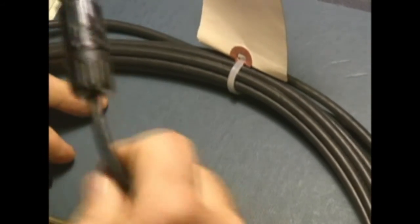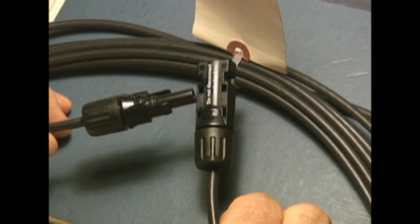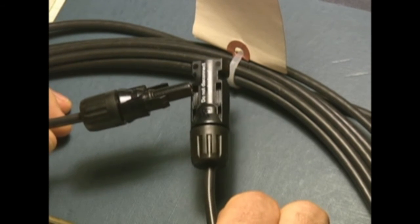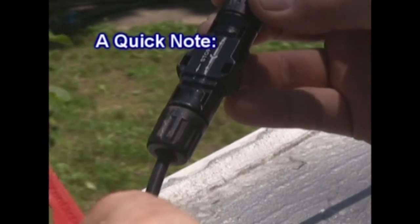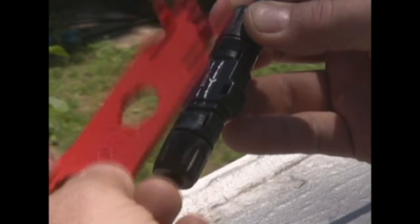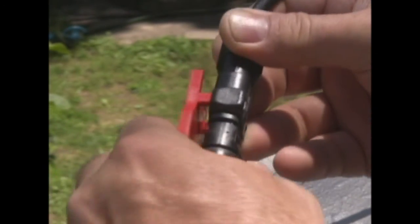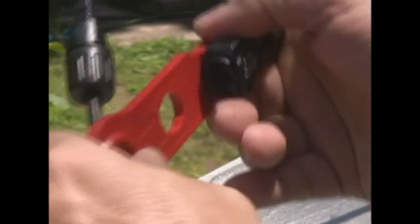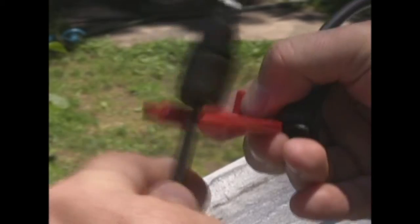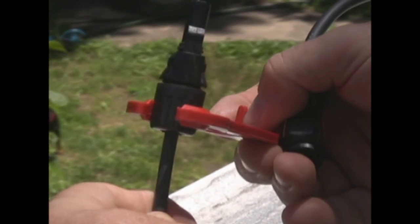How you're going to do it is by buying an extension cord like this. You're going to buy a 20 or 30-foot pre-made cable, which you can cut in half and then strip the ends and recombine them to make adapters for the plus and minus as needed. And here's the MC tool. You're going to need one of these to actually take connectors off. You insert it right into the side of the connector, and that allows you to release the connectors. The tool also has other uses, and one of the main ones is to tighten or release the end cap on the connectors.